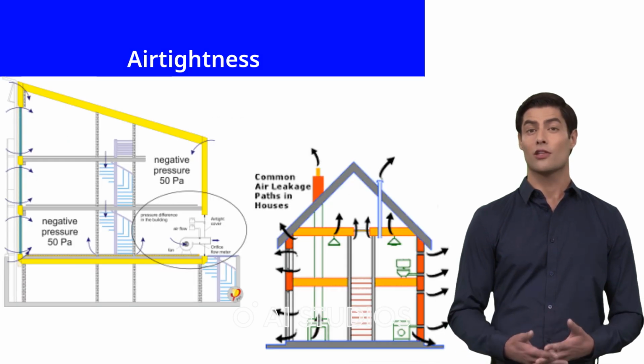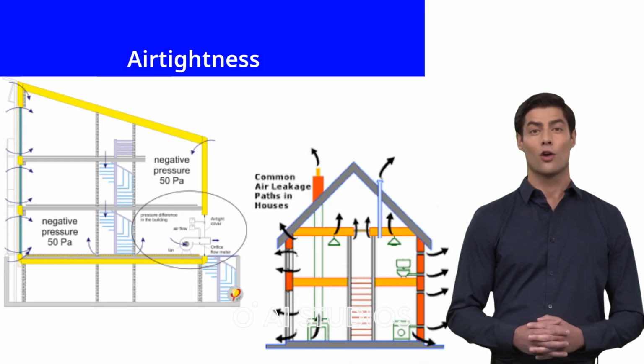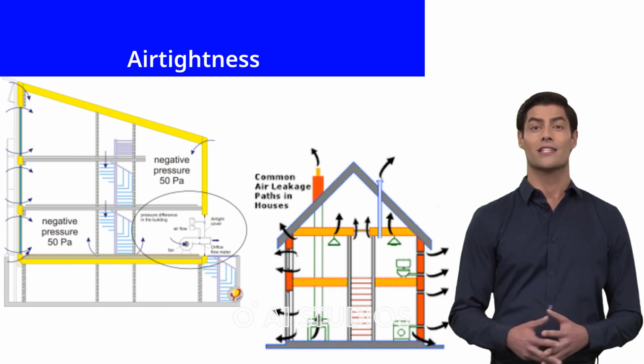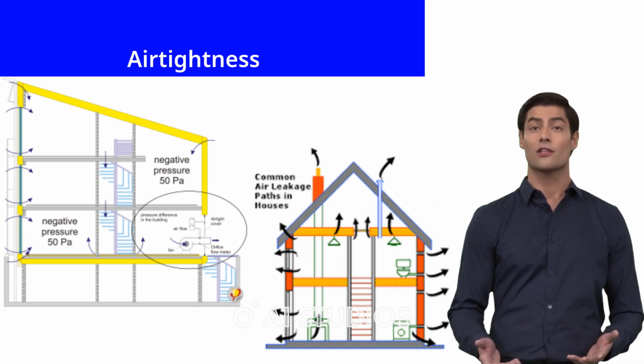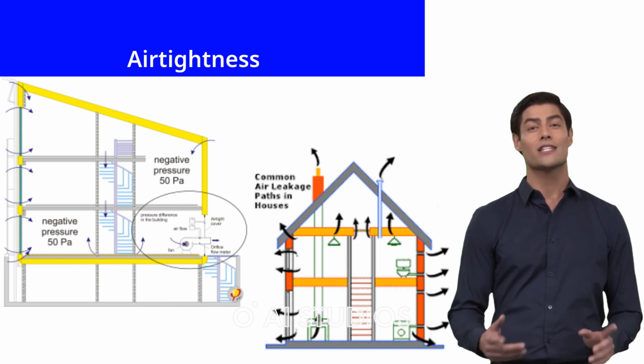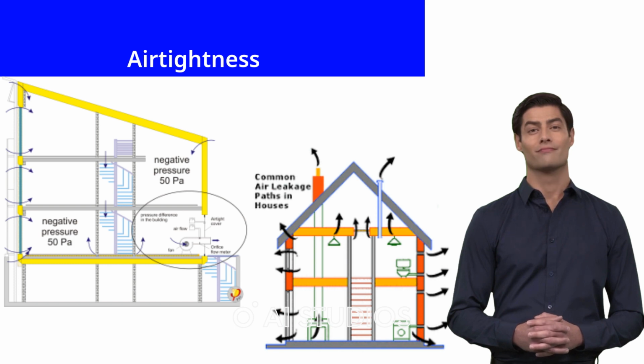Passive houses are built to be exceptionally airtight with no or very little air leakage. A continuous air barrier is installed to seal all the gaps and joints built around the building exterior to minimize drafts and reduce heat loss through air infiltration.